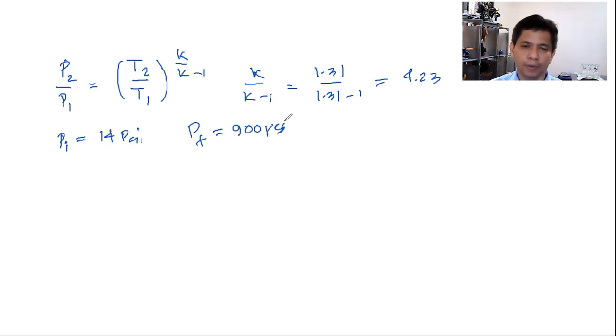Now, you're not allowed to have a pressure ratio greater than 4, because the compressor will overheat, and upon overheating, it's common sense that the compressor will be damaged. When the pressure ratio is high, the temperature ratio will be very high too, so it will result in damage to the compressor. So generally, we limit the compression ratio to 4.